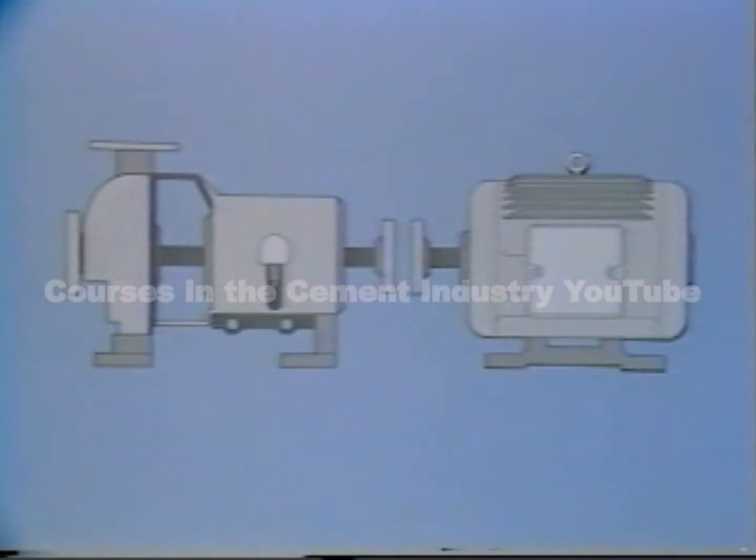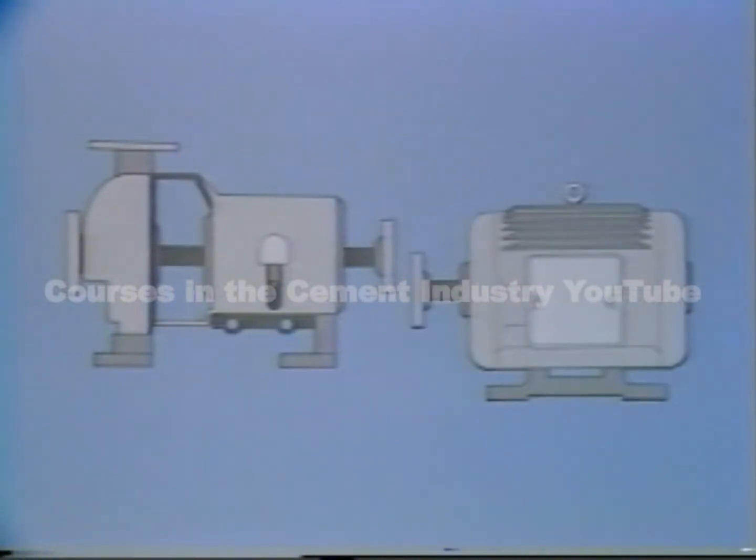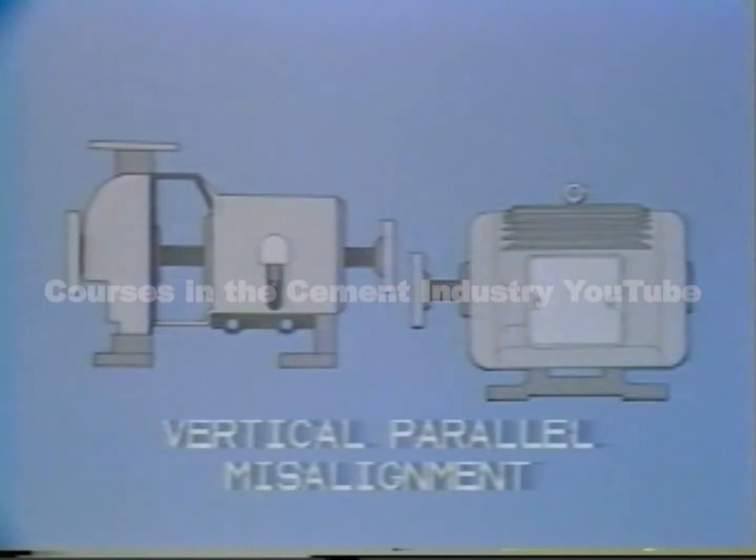When parallel misalignment occurs in this plane, it means that one shaft is simply higher than the other, like this, or lower than the other shaft, like this. So this is called vertical parallel misalignment.